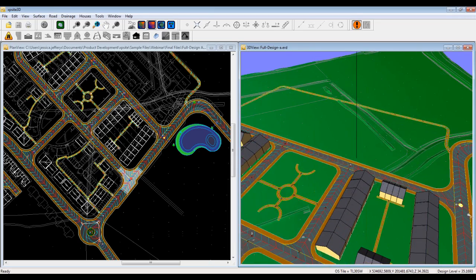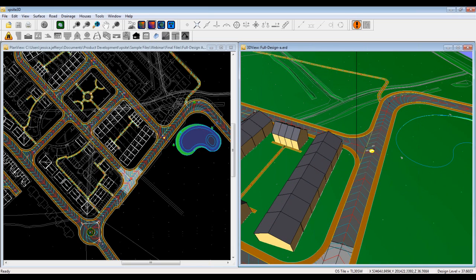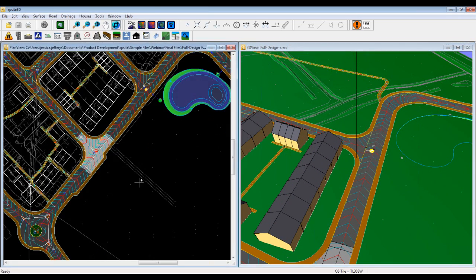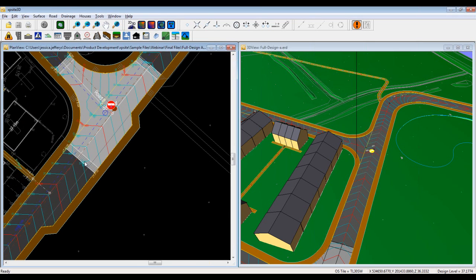So if we zoom in here, we'll be able to see what it is we're going to design. And already we've got included one road widening in the road just here. That road widening we can tell by the contours. See, we've got the speed bump there. But we can tell by the contours that road widening shares the same grade as the existing road channel.